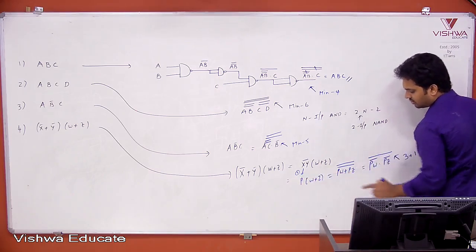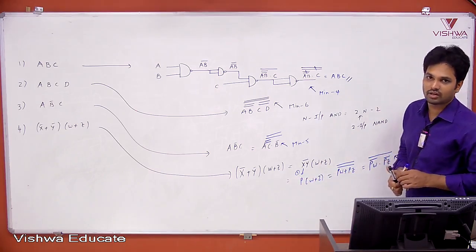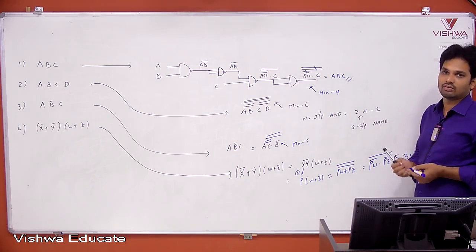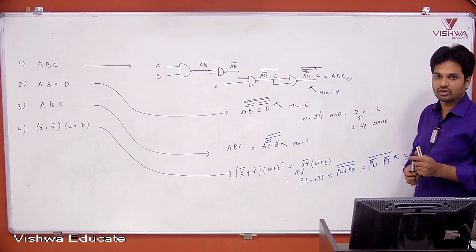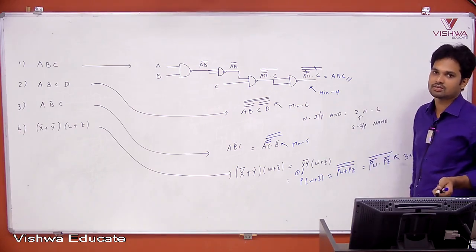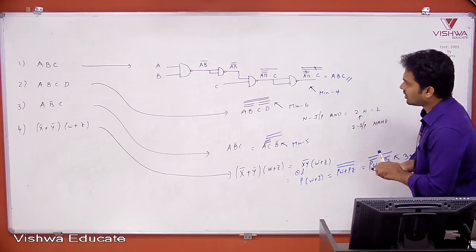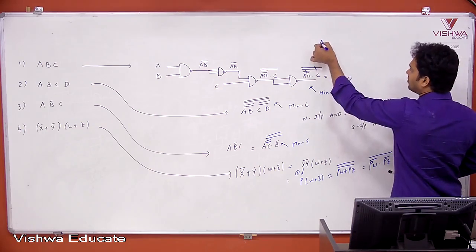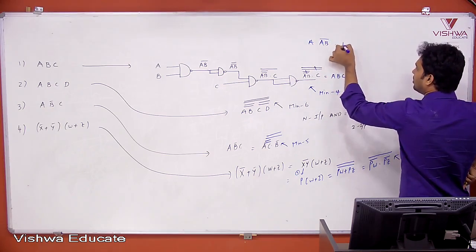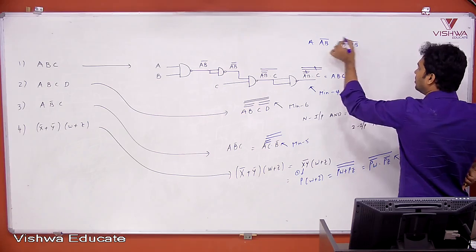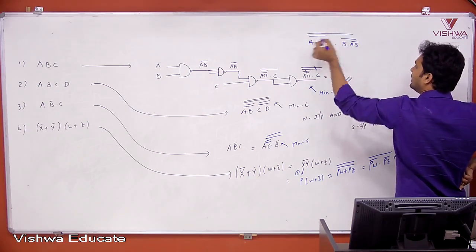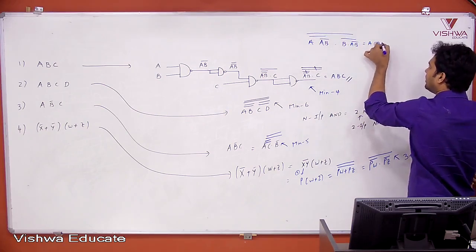To make P. Okay. So this is one way to find the number of 2 input NAND gates required to make any function. If the function is in the form of product terms, you can use this shortcut directly, counting bars. Earlier we have done the XOR gate, if you remember: A into AB bar dot B into AB bar, this whole bar. This is A XOR B.